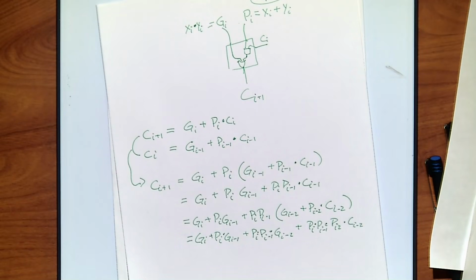And you work together with what you get from the carry in from the previous level. So those four: one half adder level, two levels to generate the carry, and one level to bring it back in. Four levels.